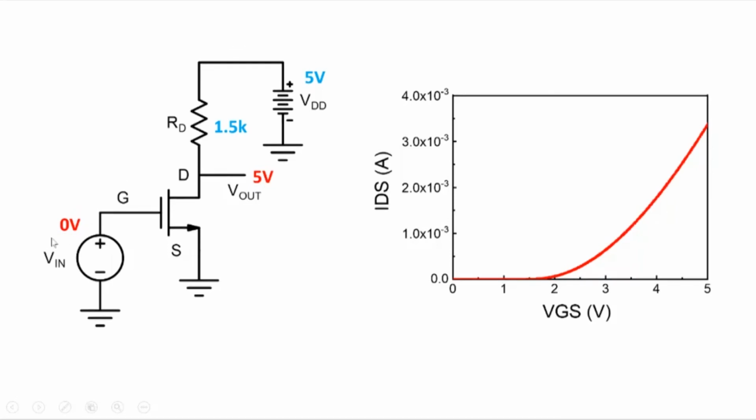So all right, now let's remove it. Let's apply a high voltage here, 5 volt. So when I apply 5 volt here, you go back to 5 volt here and you have currents in milliamperes flowing. Let's say 3 milliampere flows here, or something like that. So 3 milliamperes multiplied by 1.5K would be around 4.5 volt. So 4.5 volts drop here. So what will be remaining is about 0.5 volt here. If it's a little more than 3, the voltage here would be less than 0.5.